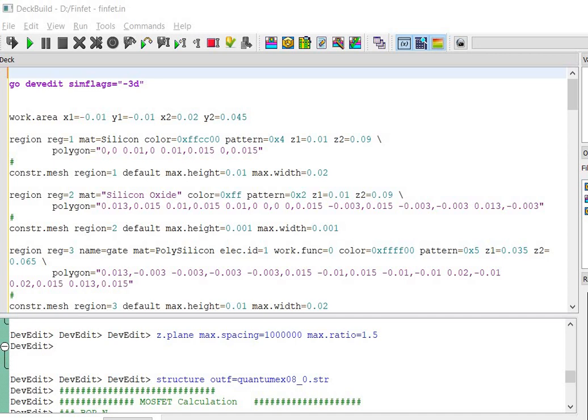There is a difference between a Silvaco standard file and a DevEdit file. In the case of a Silvaco standard file, a mesh describes the device and after that a region is defined with material. In the case of DevEdit, a DevEdit file contains the DevEdit cards needed to create a device, the analytical impurity functions, mesh creation and DevEdit mode settings.